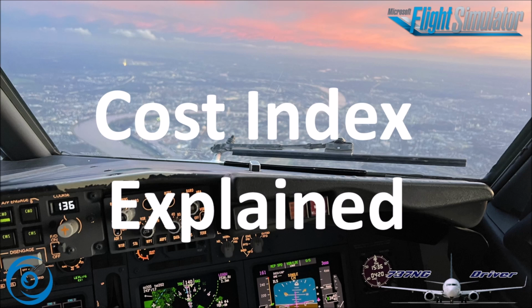So let's have a look at some typical numbers resulting from different cost indexes. Now, I'm going to do this one for a Boeing 757, since I have original Boeing numbers here in the Boeing document, and I want to stay as close as possible to it to eliminate any possible, let's call it, misconceptions that pilots might get, because there is a large influence of the speed that you are going to get from the cost index depending on the wind.